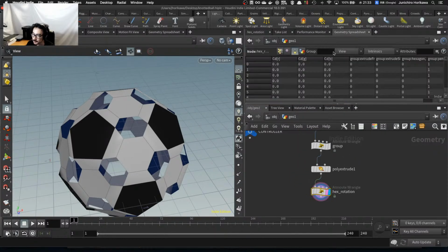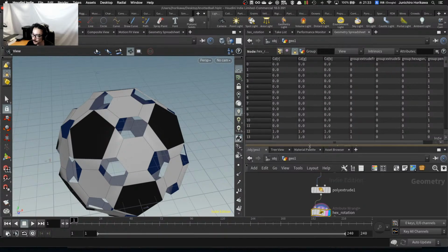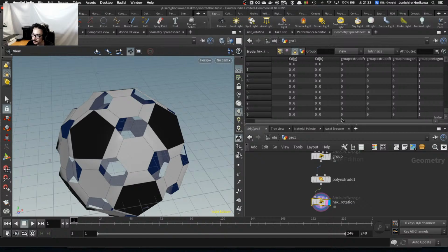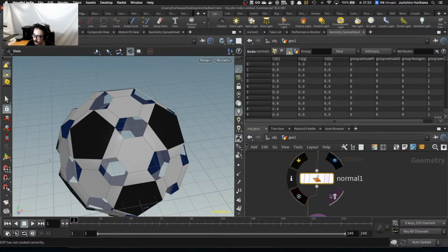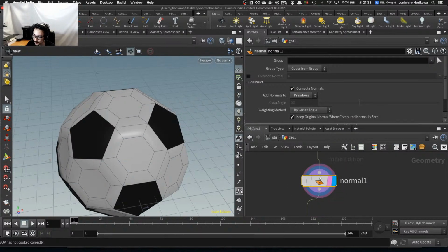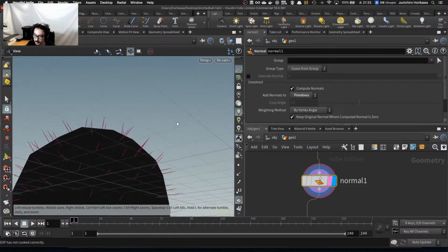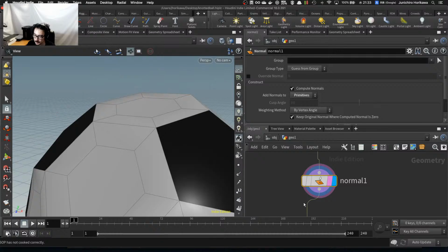If you look at the primitive geometry spreadsheet of the primitive attribute, I don't see any normal information, so let's add that information before using the primitive wrangle, and set the normal node to primitive, which should create a surface normal like this, right?